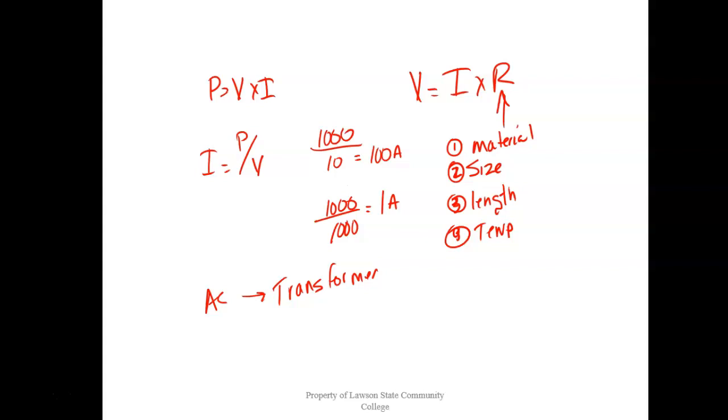If they step it up to 750,000 volts, they could send 750,000 watts of power with 1 amp of current. So what does that mean now? Well, it means now instead of using copper, they can use aluminum, right? Saves them tons of money, right? Also, it's a lot lighter, which means the towers that support it don't have to be as heavy, so it's twofold, right?